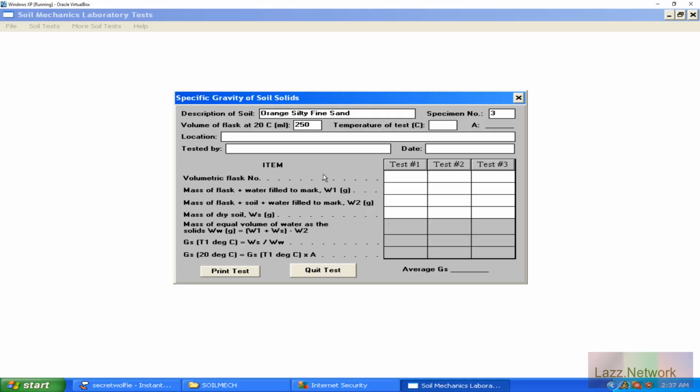Other than that, most people, at least in our industry, usually don't bother with the scribe marks on graduated cylinders or anything that has graduations. Typically, we just weigh it, because that's your most accurate thing. It's what it is at that time for the temperature and the density of your liquid that you're weighing or